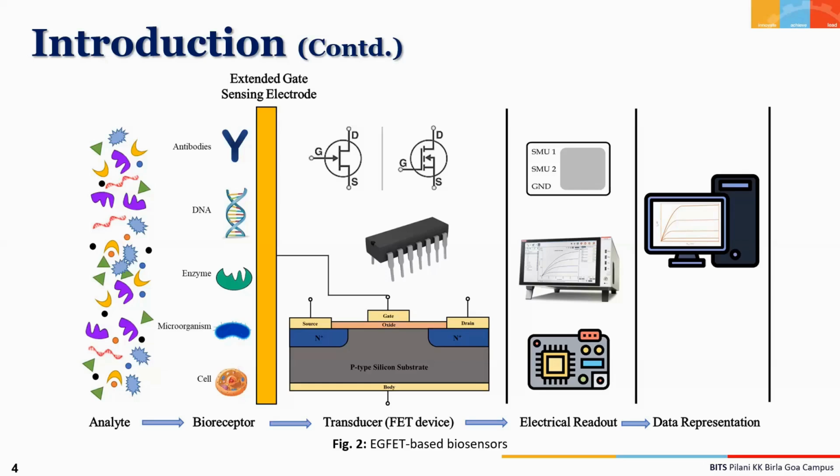Thereafter, we can connect this extended electrode as a gate, and then we can read the transfer and the output characteristics so that we can quantify this binding effect.